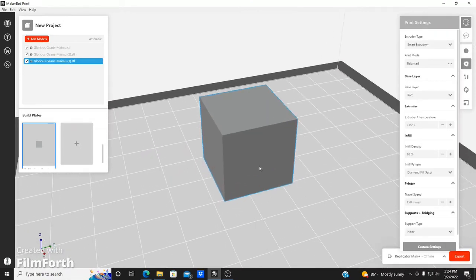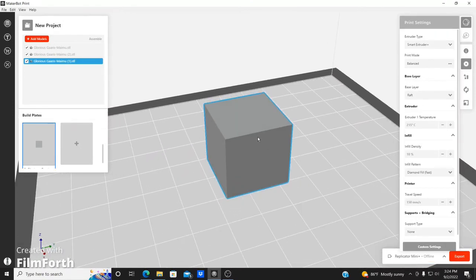So for example, this right here is a solid piece, but for the inside, if you want to add infill of a certain percentage, it will go by the percent. 10% is less material, but if you go by 50%, it'll be a lot of material. So it'll be a little bit close to being almost filled up like a solid piece, but there'll be enough gaps of holes inside. I'll show you that one next time. The next one right now after this.